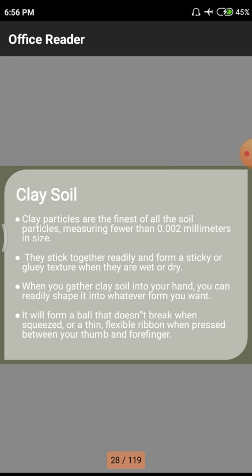Another one we have is the clay soil. In clay soils, the particle size is very small compared to the first two materials, that means silty soils and sandy soils. The particle size is as small as 0.002 millimeters, that means very tiny particles. Normally, this kind of particle has a huge amount of binding properties. They will stick to each other because the fineness is very high.